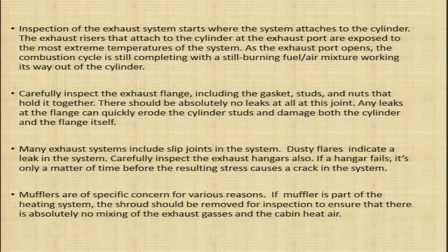Mufflers are of specific concern for various reasons. Now, mufflers, they are a very important part of the exhaust system. We need to inspect them thoroughly. If the muffler is part of the heating system, the shroud should be removed for inspection to ensure that there is absolutely no mixing of the exhaust gases and the cabin heat air.